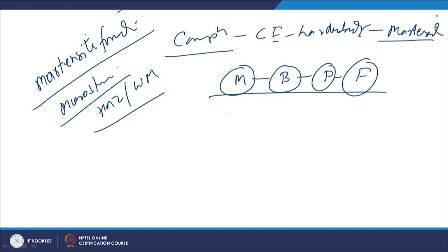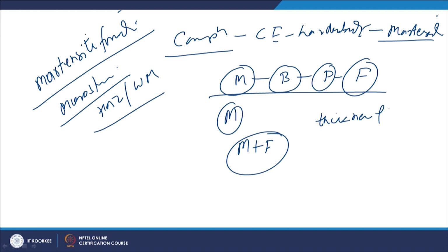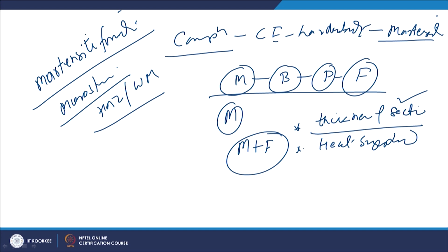So, the most sensitive is martensite, and martensite plus ferrite mixtures are also found sensitive to hydrogen induced cracking. Which phase or structure will be formed is affected by the section thickness of the plate being welded, because it determines the kind of heat that is to be supplied for welding. Greater the thickness, faster the extraction of heat from the weld metal.